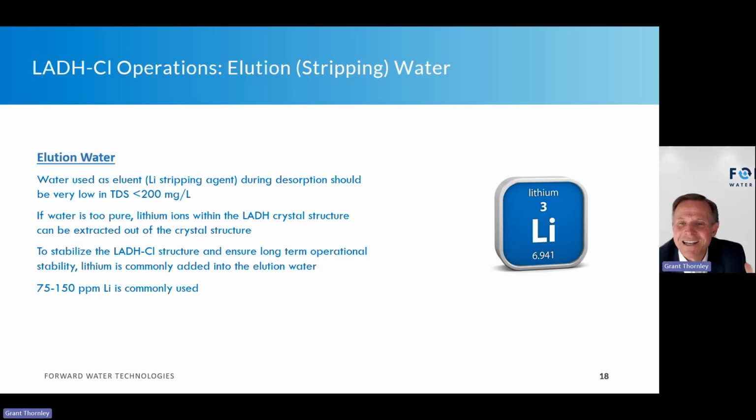However, let's say the third-party DLE media provider comes back and says, oh, I've got 90% lithium recovery. You want to see the mass balance, because you want to make sure that that 90% recovery isn't partly because you're pulling lithium out of the lithium structure. And I'm telling you that if you're only using water as your eluent, there's a very high probability you're pulling lithium out of the crystal structure.